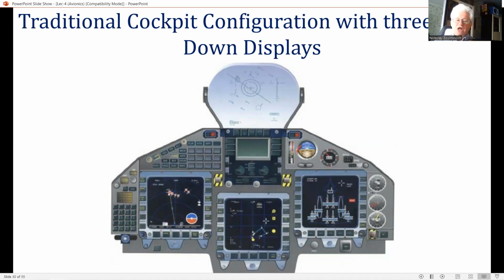There are 2 large color displays: a horizontal situation display, HSD, providing a 6 to 8 inch map display in portrait format with symbol overlay of routing and threat data, and a vertical situation display, VSD, providing an 8 to 6 inch infrared video display showing targeting video at various magnifications.